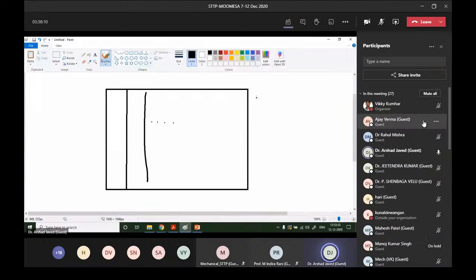So there are a total of 10 in this direction, 10 in this direction. And the total big beam is discretized into 100 elements like this. With 100 elements, I was not getting very smooth boundaries, but though it was working pixel-wise, it was okay to start with.